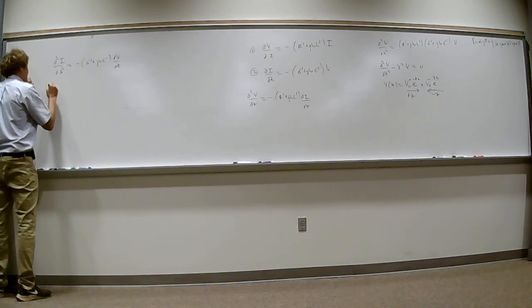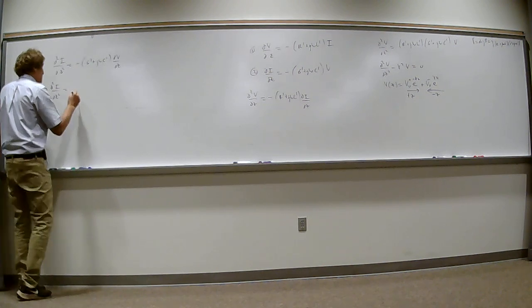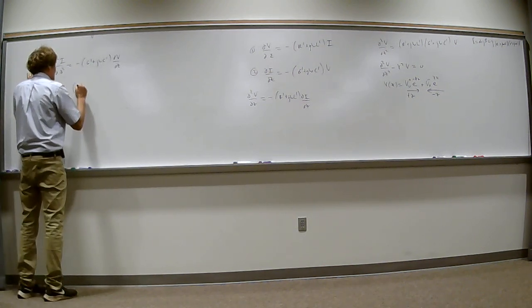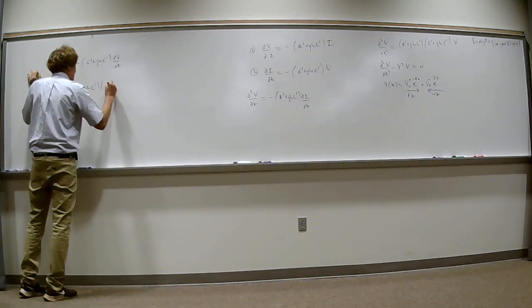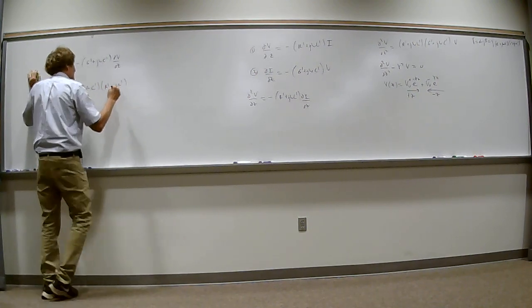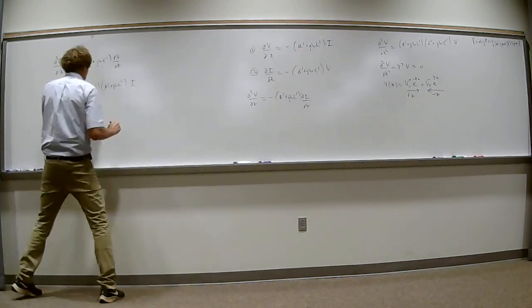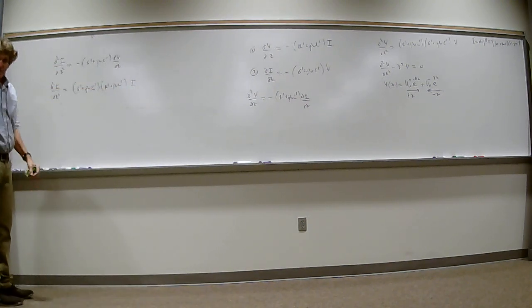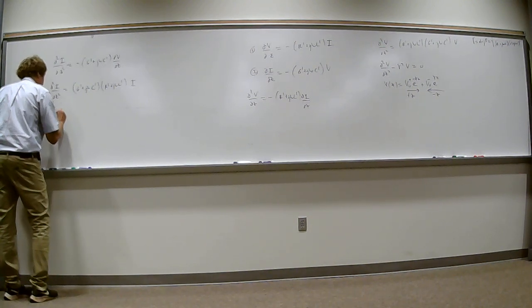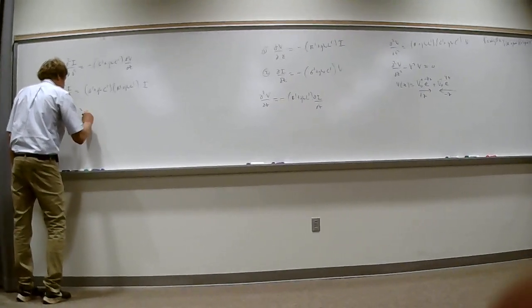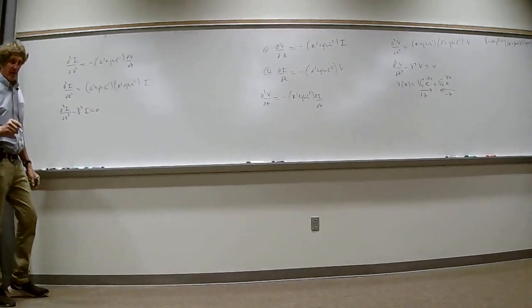So now I have the second derivative of I with respect to z squared is equal to, the minus goes away, and I have g prime plus j omega C prime times r prime plus j omega L prime, times I. That is gamma squared as well. You all see this, class? Identical. So this becomes the second derivative of I with respect to z squared minus gamma squared I equals 0. Everybody follow me?